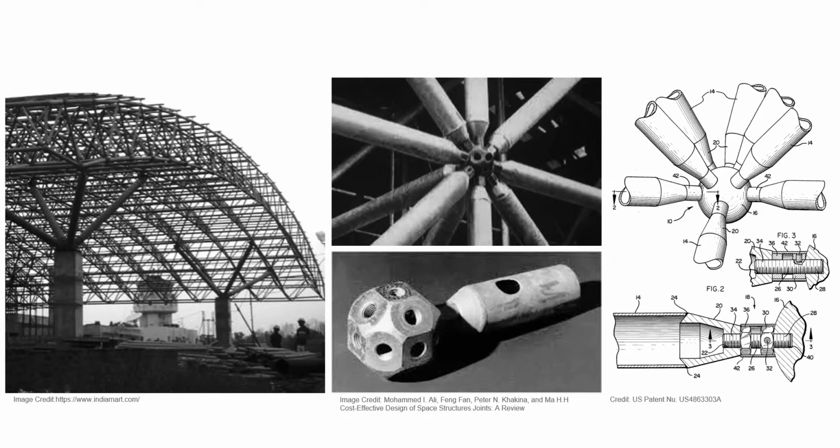Nodes in space truss systems are fabricated by CNC milling machines, commonly using subtractive fabrication methods. It means that the intended geometry is carved from a solid block of material. This approach is a highly time-consuming, wasteful, and inefficient method, though it is still the dominant way of production. The other problem facing these structures is that the position of the nodes is determined, and the elements must meet certain points, which restrain the overall geometry and network.